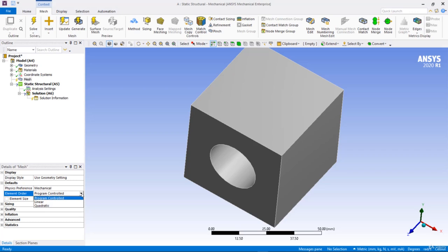as it was found that there was not much difference in the accuracy of the solution between the linear and quadratic hexahedral elements, and anyway the solution time for quadratic hexahedral elements is much longer when compared to the linear hexahedral elements. That is why it is commonly followed in the industry.